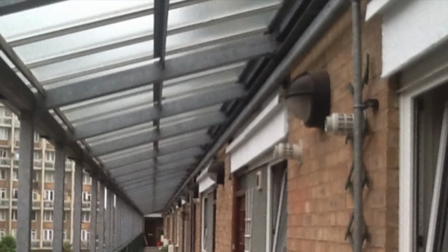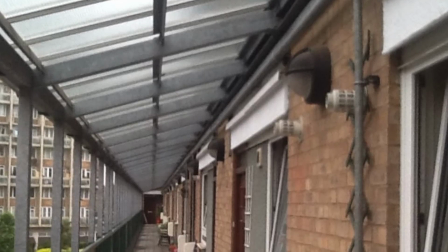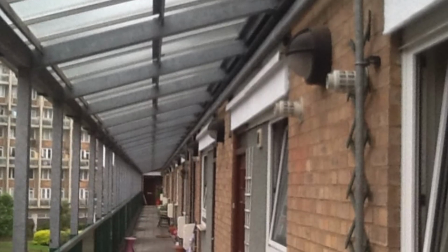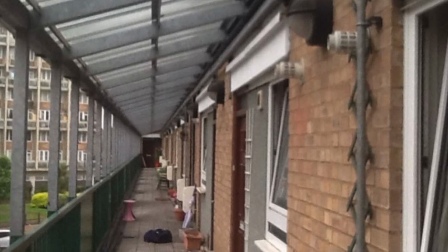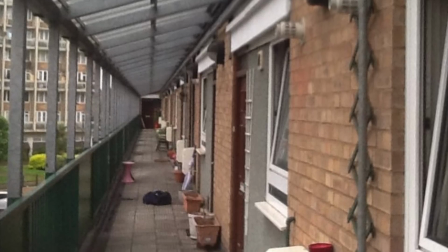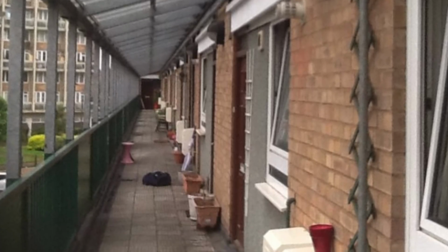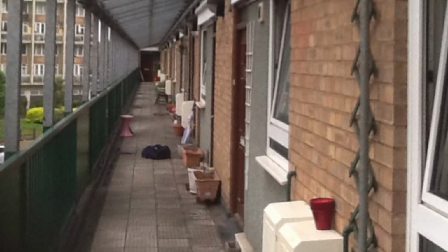Now a last look at flues which need to stick out from the wall. So if you've got something like this, which is a covered walkway, then we've got a few problems. So the first one being the flue will need to be 1200mm away from any openings within the building, like it would be under a carport.